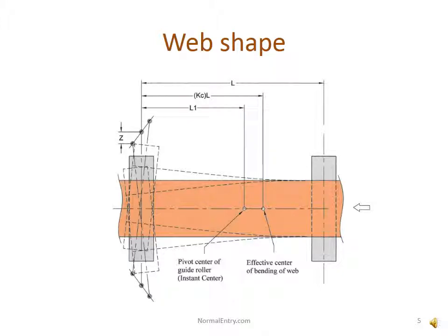The angle of entry is complicated by the fact that a web doesn't behave like a perfectly flexible string. When it's shifted laterally at either end, it bends in its own plane. The dashed lines in this diagram represent a web after it's settled down following a shift in a guide roller. The shape is like that of a cantilevered beam anchored at the upstream end, but modified by web tension. All of the bending will be near the upstream end.